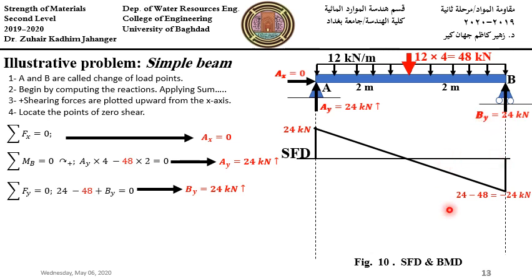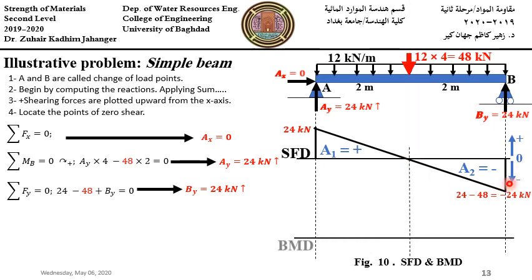Again, to draw the bending moment, between any two sections it equals the corresponding area of the shear diagram. So to start with, we need to know that positive is up. Calculate area 1 for the bending moment between A and B, and area 2 between A and the midspan and between midspan and B. The bending moment is 0 at A.